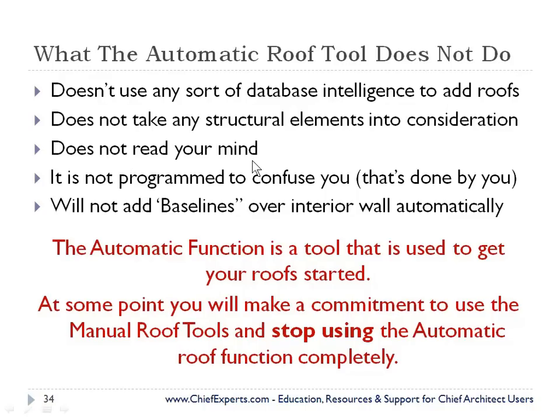Does not read your mind. It's not programmed to confuse you. Okay, that you do by yourself. It will not add baselines over any interior walls automatically. The automatic function in Chief for roofs is just there to get you started with your roofs, and that's it.